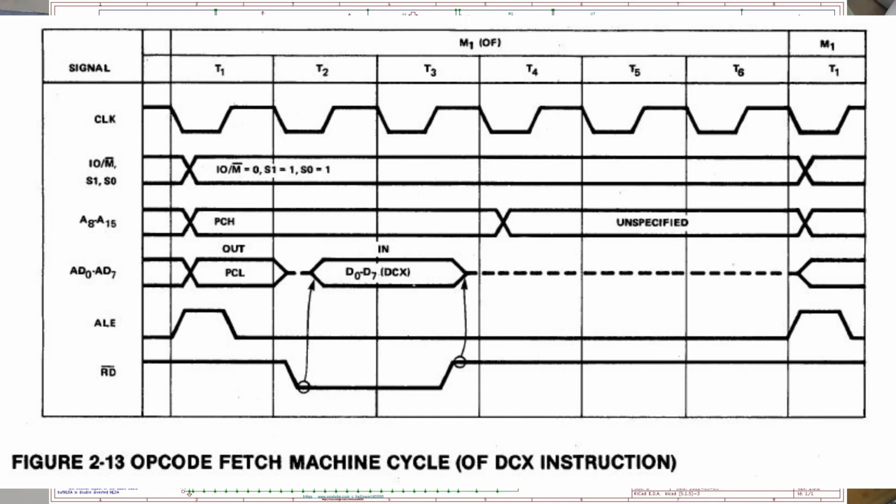And if you've ever done diagnostics on this, you've noticed that anytime you pull from a floating bus, you're most likely to get the value of the last thing that was driven onto the bus. And in this case, that value is going to be the low byte of the memory address, since the low address byte is what was just on the address data bus before the processor tri-stated it when it switched from an output to an input. So in that case, rather than getting the opcode FF, if the next instruction memory address happened to have the low byte as 56, then you would get the opcode 56, because the floating bus will give you whatever was there last.